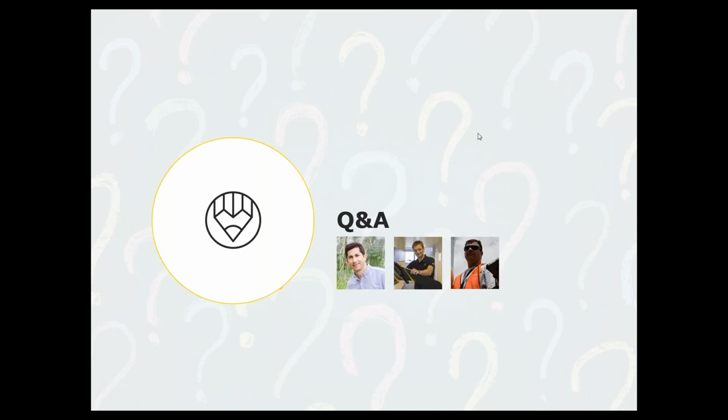Yeah, thank you for the question. Yes, it's important. It's measured. It's something that is used. I mean, geolocation XYZ is essential, and then this information will be used just to set the block, to speed the processing, and to make the reconstruction faster. It doesn't need to be extremely accurate, but it is part of the georeferencing. There is the geolocation, which is XYZ, and there is the attitude, that both are recorded in the metadata of the image. So it is there. It wasn't shown, but it is there in the processing, yes.